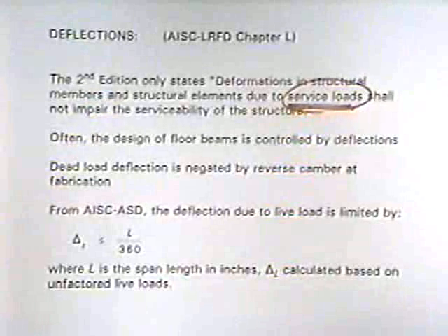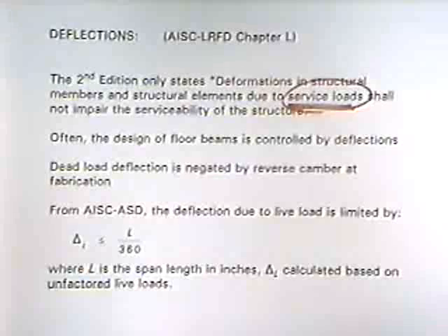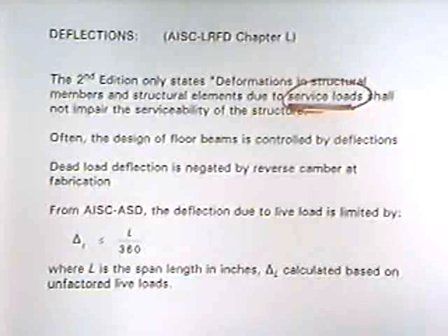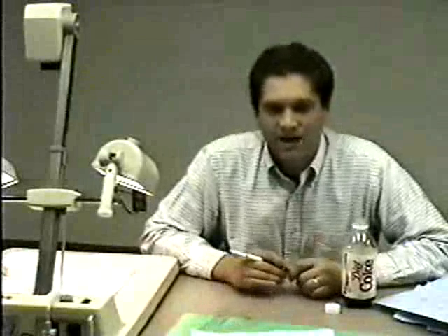Okay, what we don't want to happen is the floor to vibrate or deflect excessively when we're using that building under normal use. So don't factor up the loads to do that calculation. If you went out to the naval base at Subic Bay, near Mount Pinatubo, I can guarantee you they couldn't care less how much deflection they got in their floor beams when that volcano and the earthquake and the typhoon were occurring at the same time.